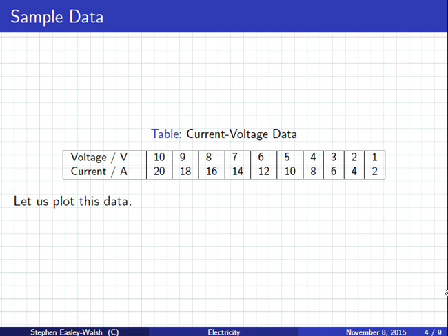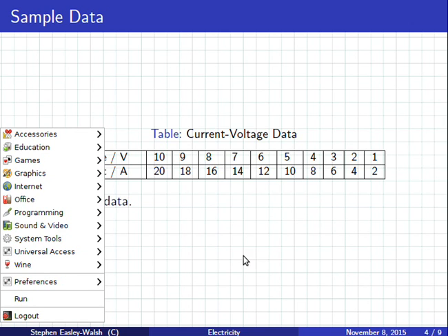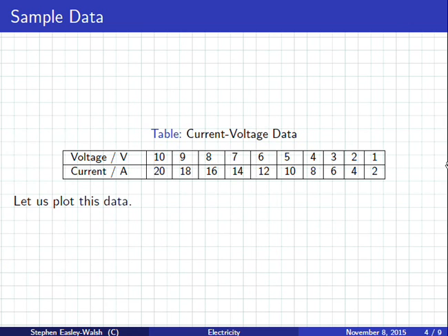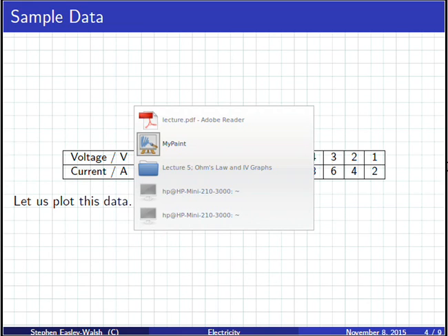So, what you're going to do for this experiment is make a table of voltage and I. By changing the resistor, you get different values here, and then you can get different values here. Now please note, you can get better equipment.